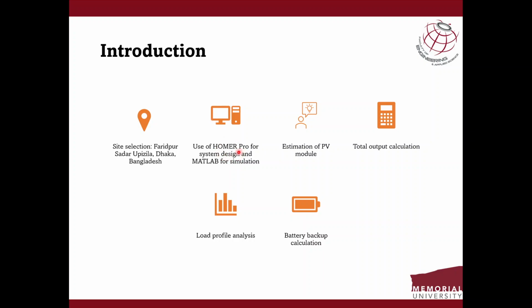By doing this HOMER Pro simulation, we get the estimation for the PV module, and then we have calculated the total output and analyzed the load profile depending on our solar pumping system and its capacity. And finally, we have estimated the battery backup for 2 days or 3 days, whatever the consumer wants to take as backup from the battery.